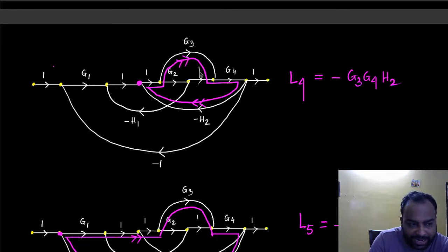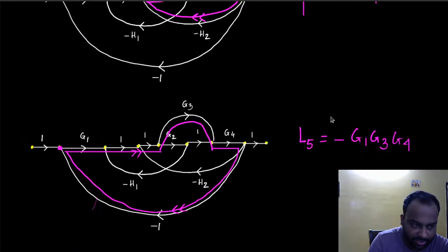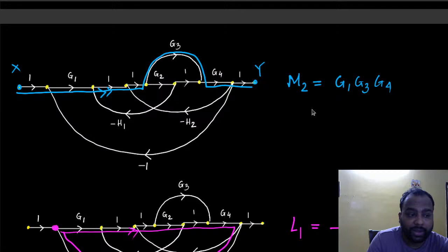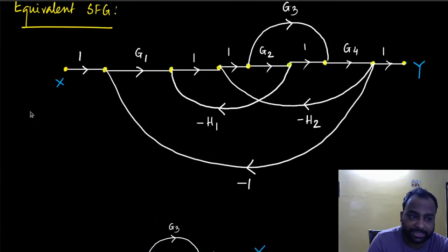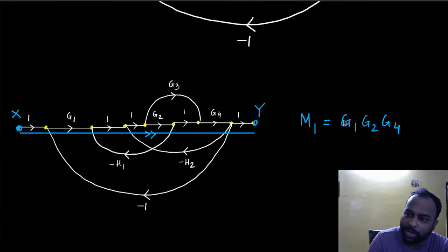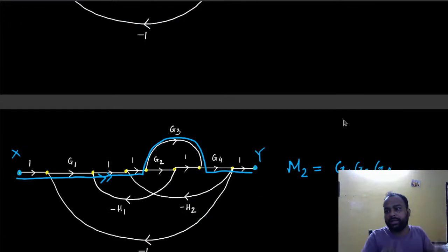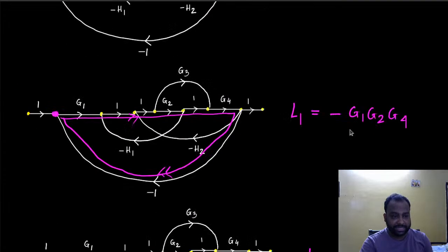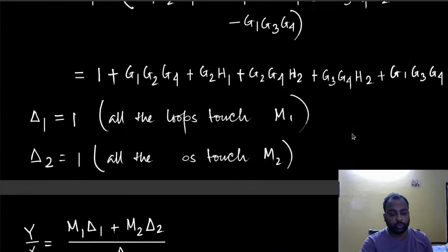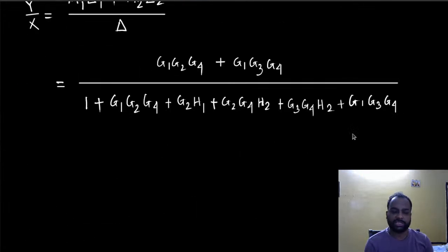By looking at that, you would figure out which loop you're actually talking about, right? Because of the transfer functions that are there. So that way you don't have to draw everything repeatedly. Just by drawing this, you'll be able to calculate everything and then combine everything together, right? So this is essentially a single step method through which, without any cumbersome calculation, you can figure out the transfer function of a whole complicated system.